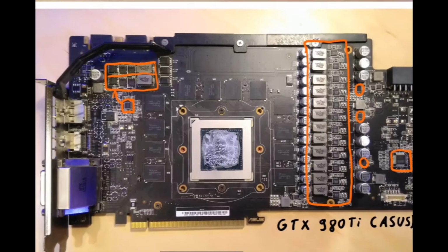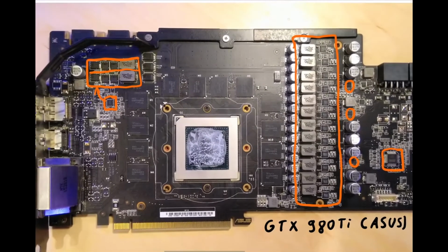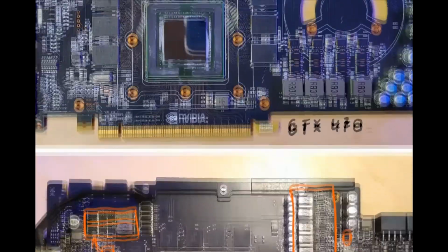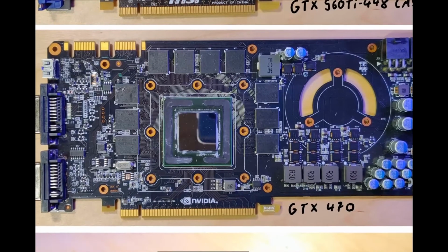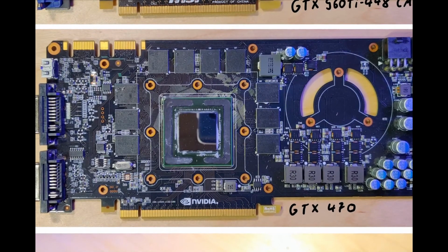And what's also interesting here is vCore is using power stages, whereas VMem is using discrete MOSFETs. Most of the time you will see that both VRMs use the same MOSFETs or power stages, but it can also be something different, like on this card. So then we have our GTX 470 reference PCB with our 90 degrees rotated VRM. This is a 4-phase, as I've already said, and then a 1-phase VMem.